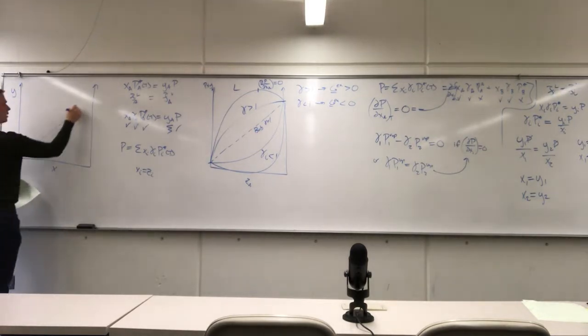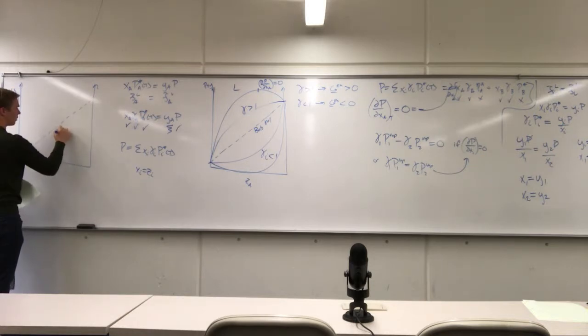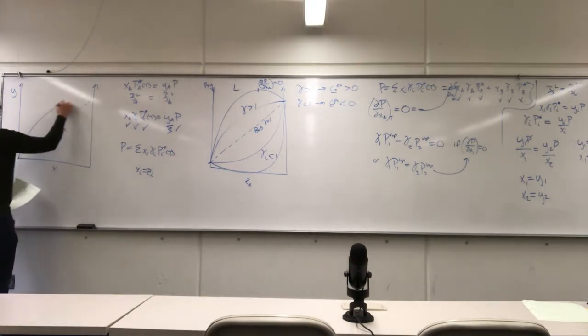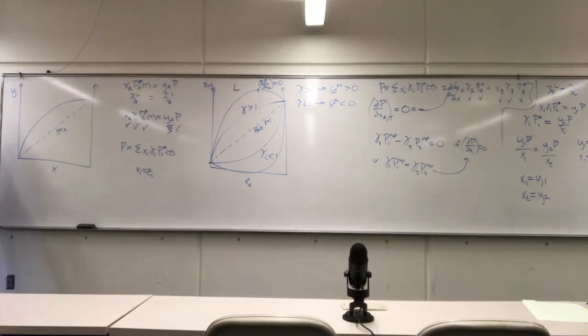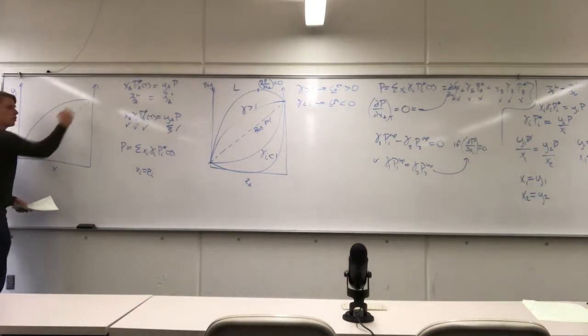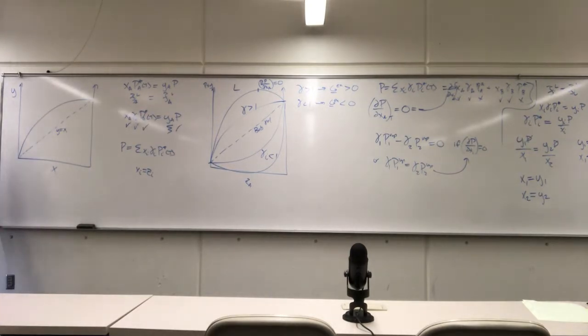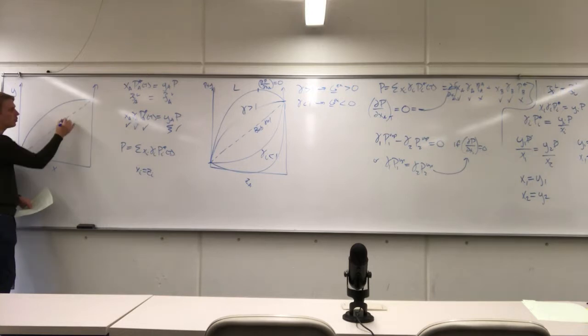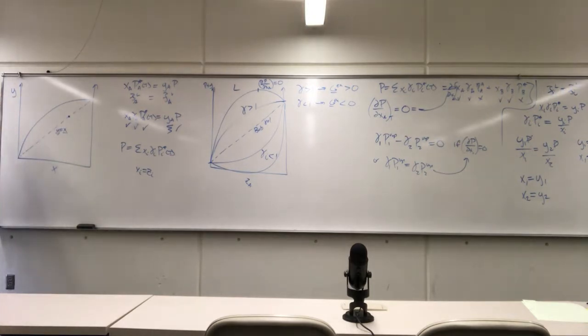we have our line here. This is our y equals x line. So for a normal material, it looks something like this. And we counted out the equilibrium stages. We go 1, 2, 3, 4 stages, and we can do the separation. But in the case of an azeotropic system, we're going to have a condition where x is equal to y, which means that we're going to fall on this line.